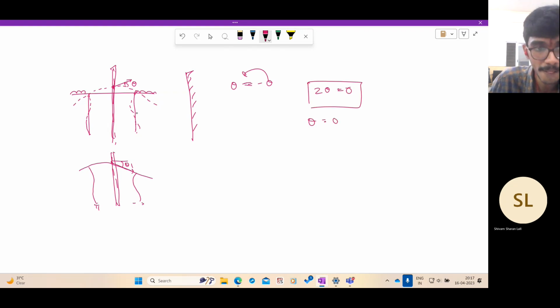So along this plane, if you have a u and you take a mirror image of the same structure about the symmetry plane, the u will become minus u and theta will become minus theta. But v will remain v only. That is the beauty. If it deflects upwards, since it is lying on the mirror plane, it will remain v only. So v will not be 0. U will be 0. Theta will be 0. V will not be 0.